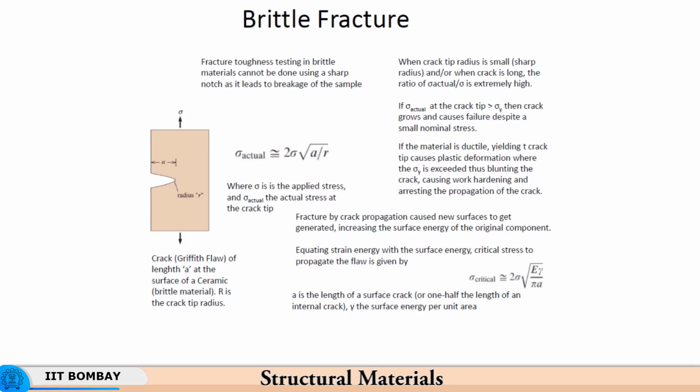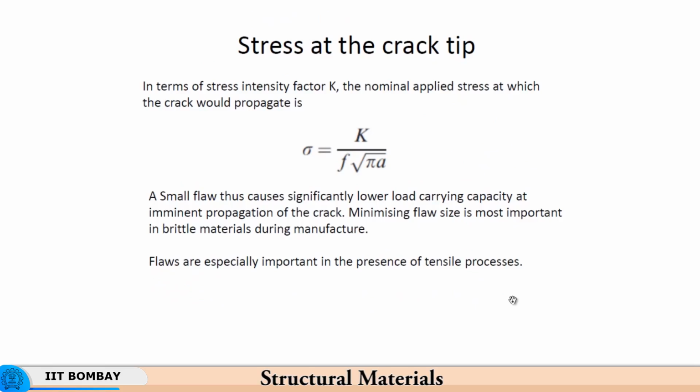As long as the crack does not propagate, as long as the flaw does not get enlarged in size, you can still use the component or the material. So, in terms of stress intensity factor, the normal applied stress at which the crack would propagate, sigma critical, is K upon f root of pi a, where f is a constant factor, which will be defined as we go along.